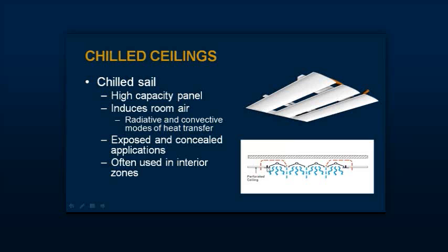So what I did was I dropped the air volume down to 100 CFM, which is the minimum for ventilation purposes, and then handled all the latent load with that air and all the sensible load with the water system through those sails. And it's gone from being an almost never used room to being one of our most commonly requested conference rooms, simply for one reason. It is always the exact same temperature year-round inside this space. So that I think is a very interesting product.